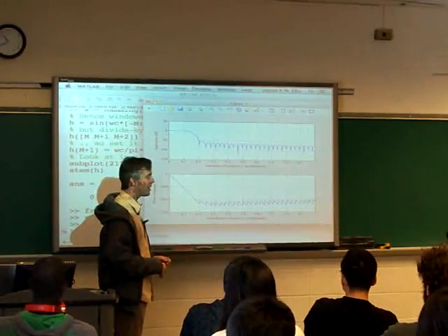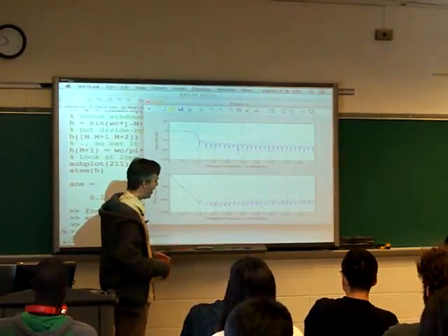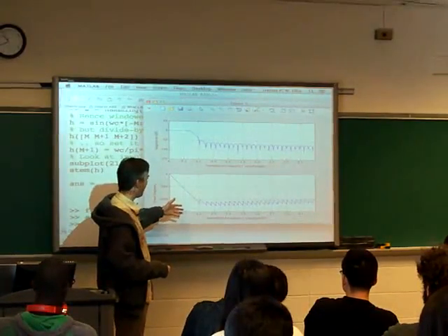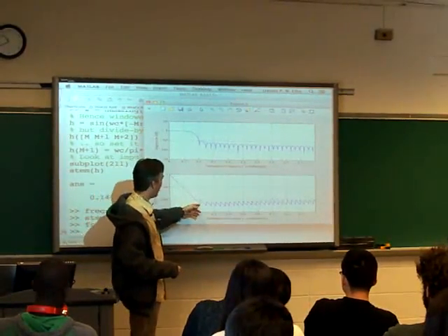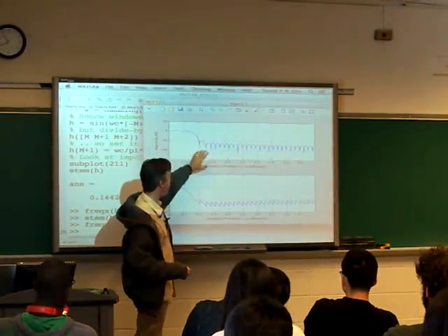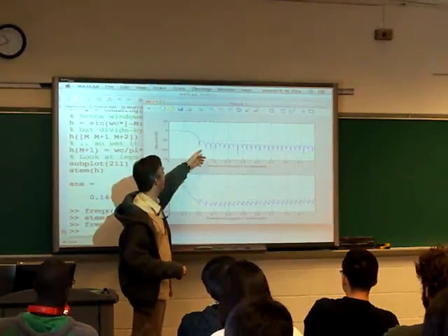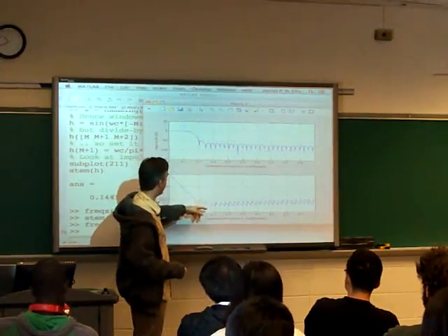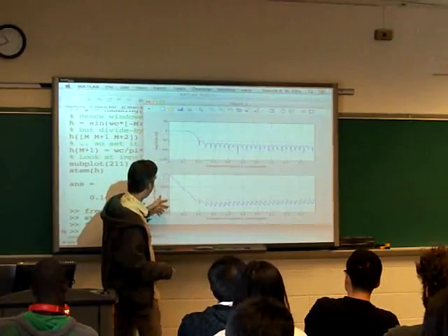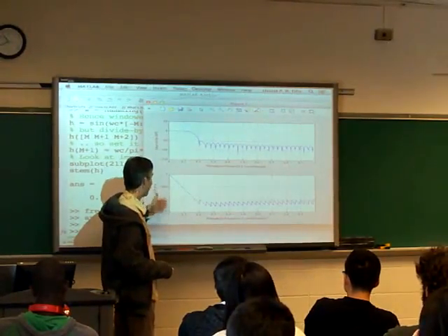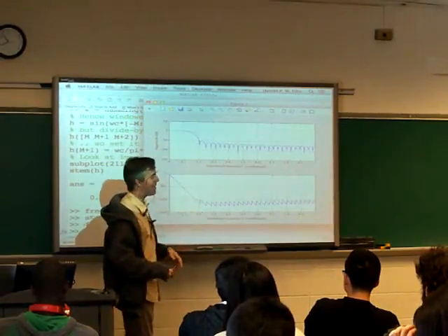It had two plots because I don't know why. It overplotted the previous one. This is the phase response, but even this isn't. You know, these little jumps here are pi-sized jumps because whenever it goes through a 0 here, it has a flip in sign to get the magnitude response always the same, and so it does that by putting an adjustment of pi in here, which is 180 degrees on this scale in degrees, which is going down to 1,000 degrees. So it's kind of a misleading plot.